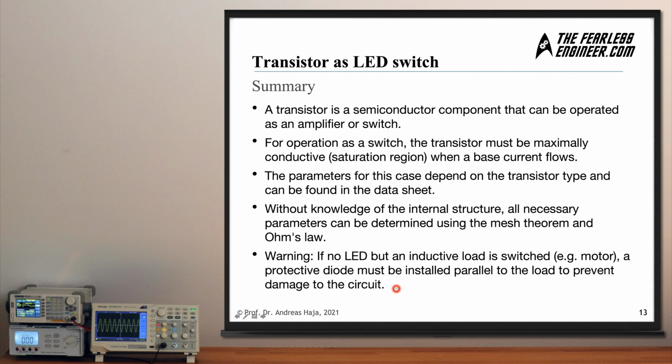But when you trigger, let's say, a relay which switches something and then you switch it off again, the energy stored within the magnetic field of the relay will backfire by means of induction and induce a very high voltage peak into your circuit, which can damage the transistor. And in order to account for this, we need a diode in order to filter out this undesired behavior.